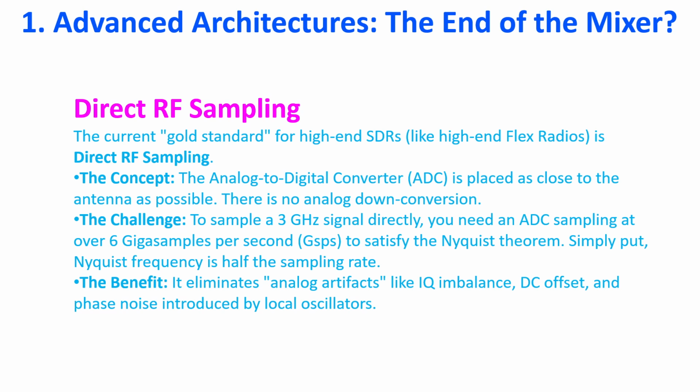In practice, the actual phase difference may not be exactly 90 degrees and the gain may not be equal in these two signals, causing IQ imbalance. DC offset is the value introduced by the DC bias so that the mean value of a sine wave becomes non-zero. Phase noise describes random short-term fluctuations in the phase or frequency of a signal from an oscillator.